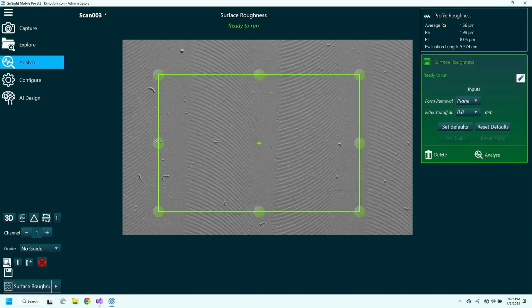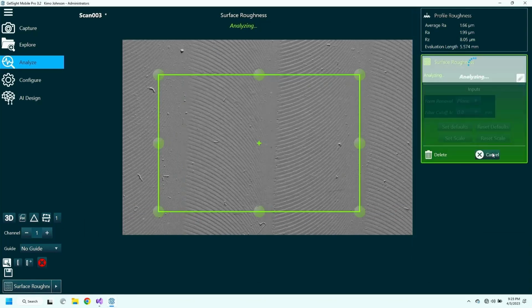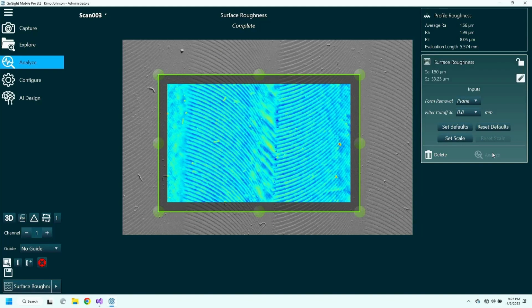So as you can see with our tool, it's a very fast way to measure roughness parameters of a surface, and much faster than competing instruments, which often exist in labs. This is a tool that can be down on the factory floor, can be used in a handheld setting, and has a relatively large area. It measures approximately 8 millimeters by about 5 millimeters in its area.